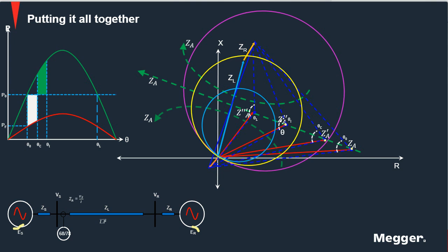And the importance of that is that an impedance relay placed here, this is the impedance that it's going to see. One of the problems is that the relay initially is going to see that the system is operating away from its characteristic, in the load area, for example here.